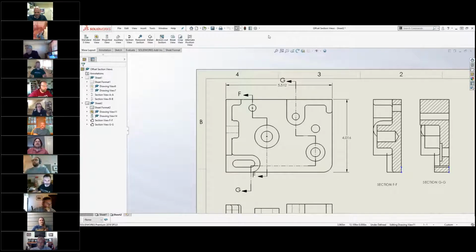With that, I will stop using this. Oh, go ahead. One last section view question. So many people I see put their section views on the wrong side of the line, the cutting line. Remove section views, move them around the sheet wherever they fit best, right? But at least for most of us using third angle projection, those are supposed to go behind the cutting line or opposite the arrows, right?